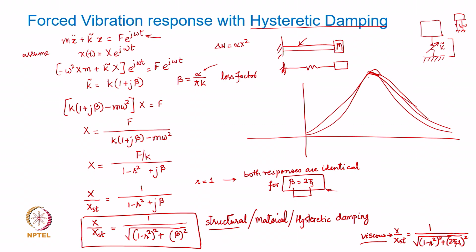And then of course, once this expression is known and you somehow through tests figure out the structural damping coefficient or loss factor, you can substitute for this parameter in this equation to find out the response at any frequency of excitation. So, broadly the two expressions are quite similar in that sense.